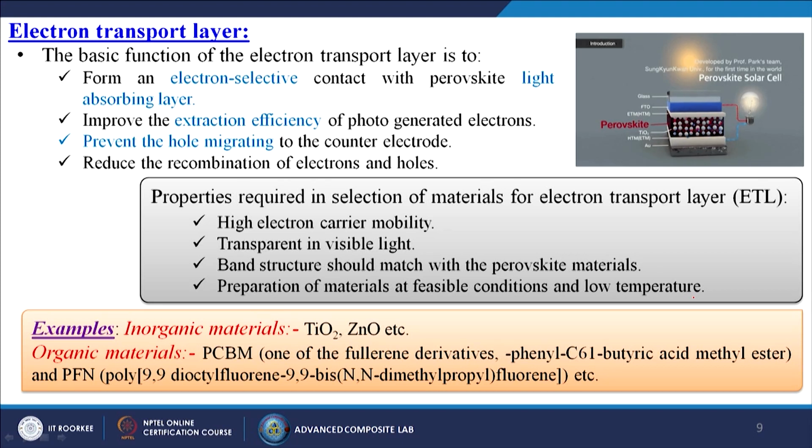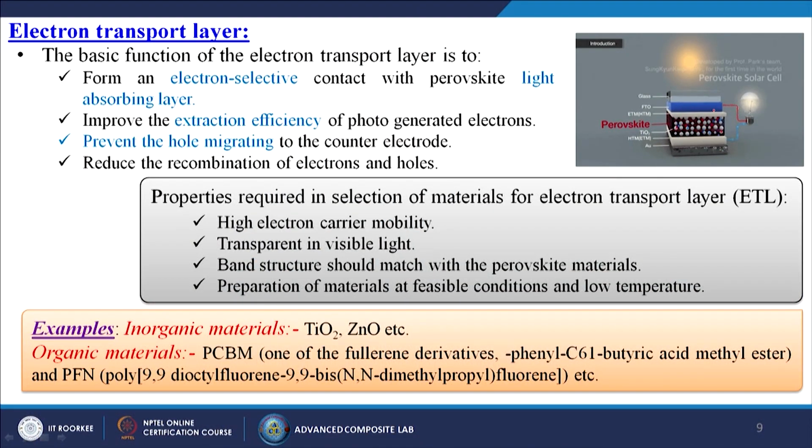So, from this particular image you can understand that this is the perovskite solar cell material. First we have gold, Au, on top of that we have the HTM or maybe the ETM materials, on top of that we put the TiO2 and then we put our perovskite material. If the below one is the ETM, of course the upper one will be the HTM, or vice versa. Then we put the FTO glass and on top of that the glass substrate. So, this way you can see the perovskite material is in between our ETM and the HTM, or maybe the opposite.